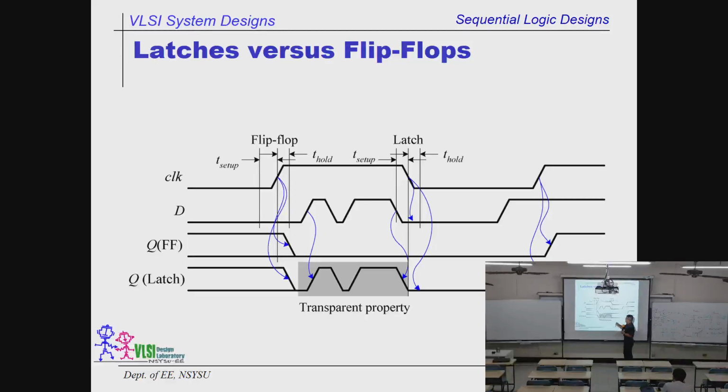The only thing we care about is when the clock or the enable signal goes down to close the latch. We have to make sure the signal is correctly sampled. Again, data must be ready and stable before T setup, and stable after T hold, just like what happened on the other side of a clock duty cycle. This is important.